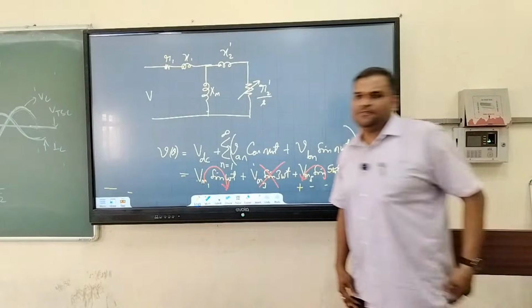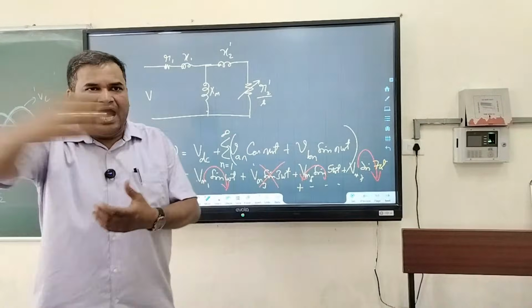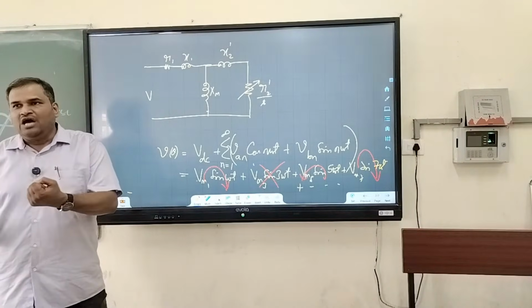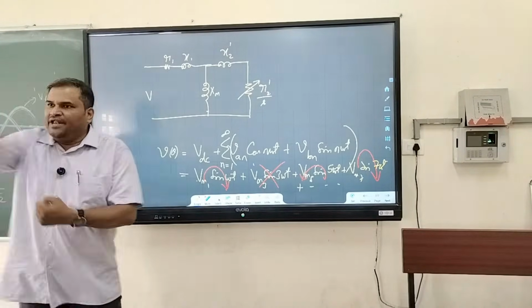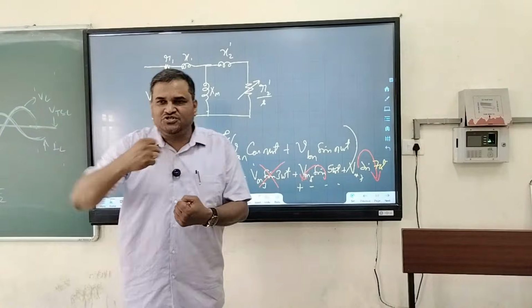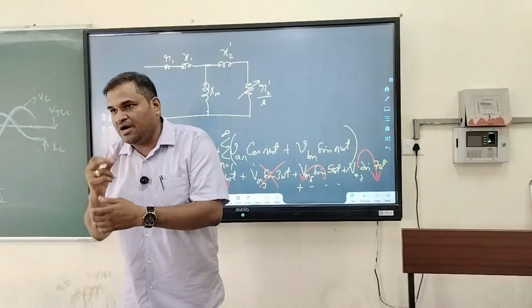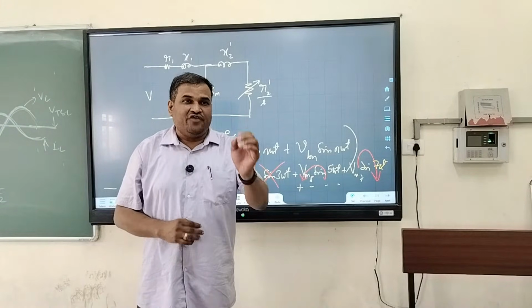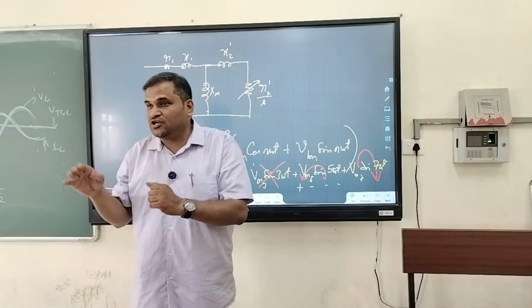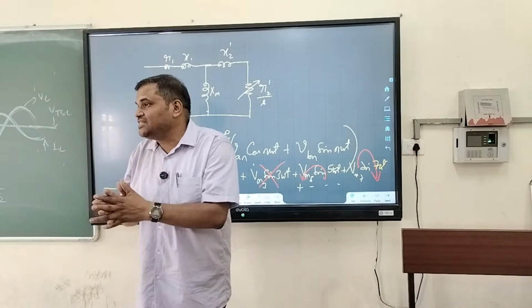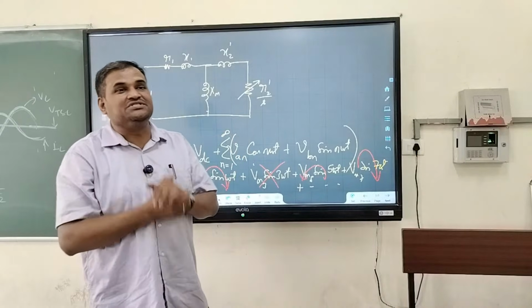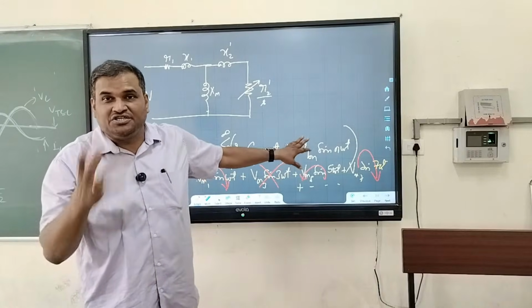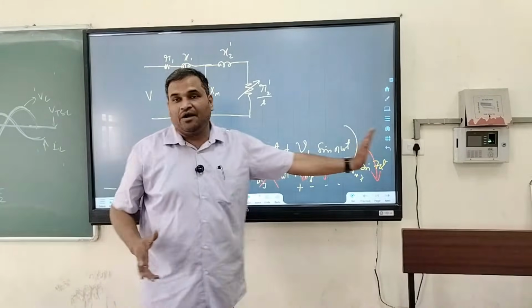That is also not okay. Because if you are rotating something, at whatever rhythm you are rotating it, a small child comes and also tries to rotate it, and if his hand moves back and forth, then your rhythm will get spoiled. So if you are using a very precise motor where the motion should be very good, sinusoidal and smooth, these seventh harmonics, fifth harmonics are the disturbances. So that's why we use a filter or a modulation technique to remove all these harmonics.